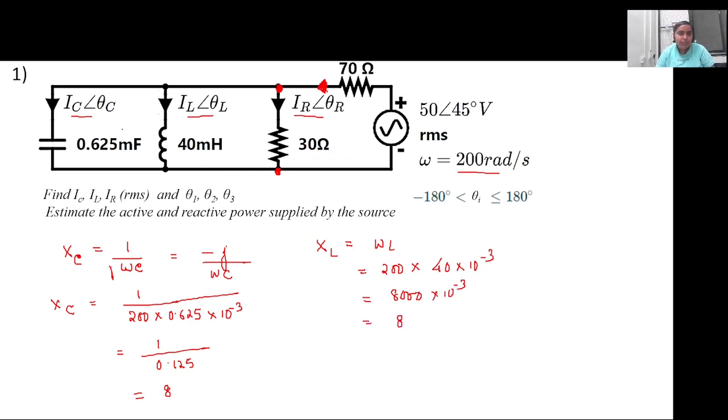If you consider the circuit up to this much, these two branches are in parallel to each other, right? Since both values came out to be the same, let us see if it is possible to get rid of this part of the circuit. Up to the point, let's say A A dash, if we calculate Z, it is XC parallel to XL, right?